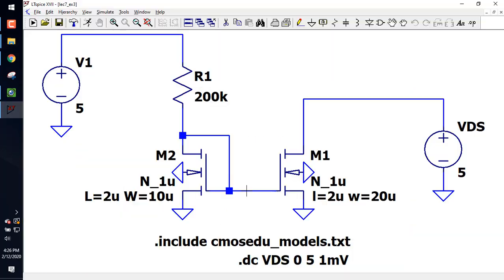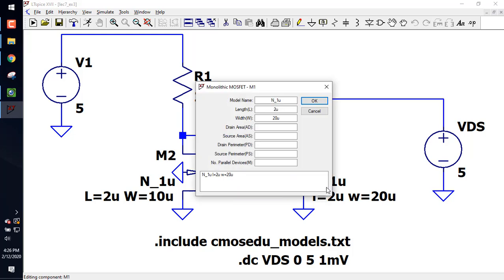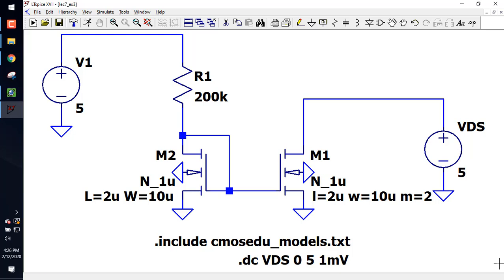They'll come over here, and instead of putting one device like that, they'll come down here and put 2 devices in parallel. So each MOSFET has the same width. Okay? And by doing that, you don't have oxide encroachment effects. And watch what happens. So you see the M equals 2. So when I say that, what's in everybody's mind when I say M equals 2? There'd be 2 symbols here. The drain's connected together, the gate's connected together, the body's connected together, and the source is connected together. But it's more compact to draw it like this. Okay, so let's hit run.